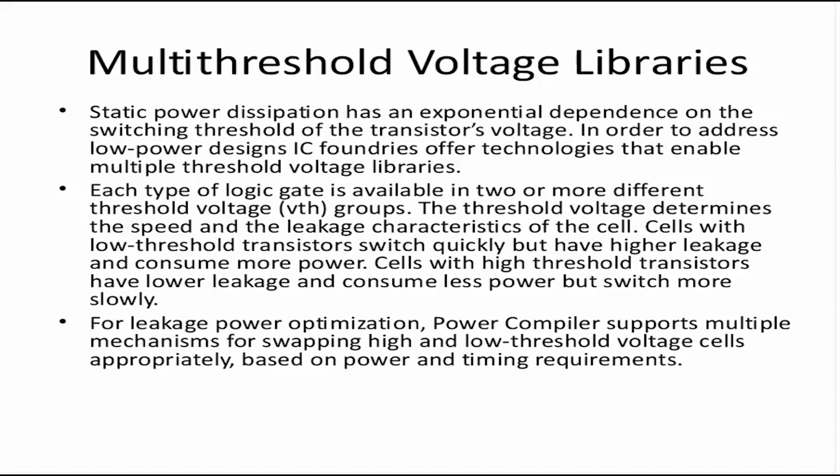In order to address the needs of low power IC design, the technology library providers provide cells with multiple threshold voltages. Earlier we saw, for example, a 2-input NAND gate. Now the 2-input NAND gate will probably come in 2 or 3 threshold flavors, right? What is popularly done nowadays is that there are 3 threshold voltages for each cell.